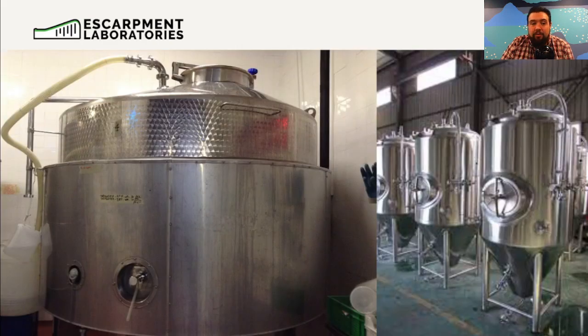Now, to give you an example on this, what we have here is two different fermenters, very different. On the left-hand side is a fermenter from a brewery called Diacetyl. Sorry if I'm saying that incorrectly. This is a wide, shallow fermenter. Now, on the right-hand side, we have these tall, skinny fermenters. These two fermenters, based on the kinetics, based on how the fermentation mechanically unfolds, are going to have different properties. How much CO2 is retained, how much pressure is on the yeast cells. These are all going to impact the flavor profiles produced. We need to make sure we compare apples to apples, not apples to oranges. We should not compare the ferment of a beer in the tank on the left to the beer in the tank on the right. You have to make sure this is accounted for.